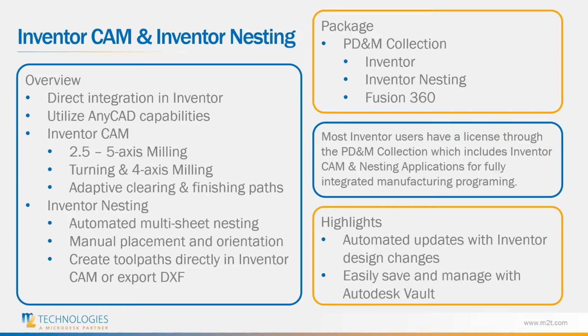So one of the keys with this is for most Inventor users, they already have a license using the Product Design Manufacturing collection and often don't realize that that comes along with CAM and nesting full integration with their product. This allows for you to work seamlessly within that one design space. And again, working within a design space, you're going to have automated updates within Inventor. So if you make design changes, you can quickly recalculate those tool paths without having to reprogram them, and you're also able to easily save and manage your data using Autodesk Vault.